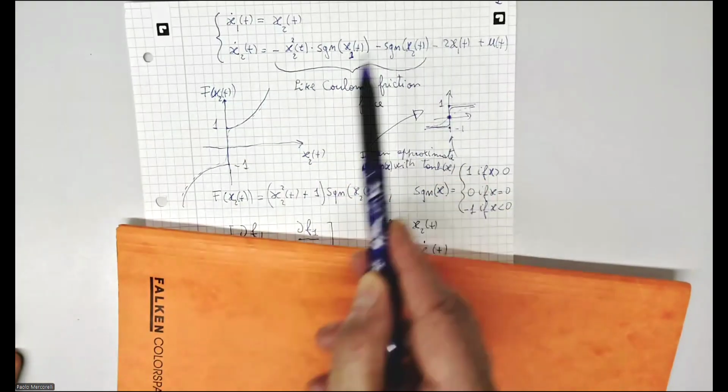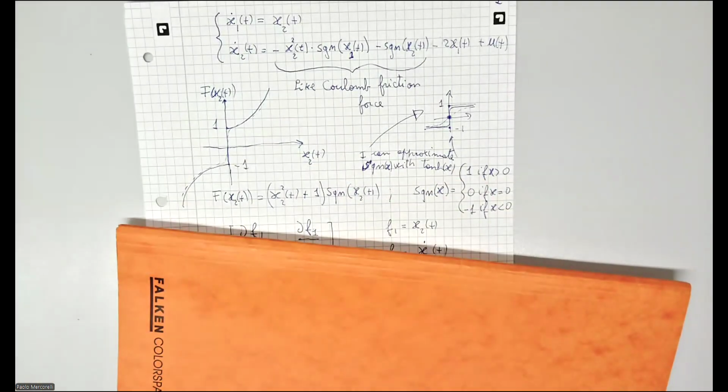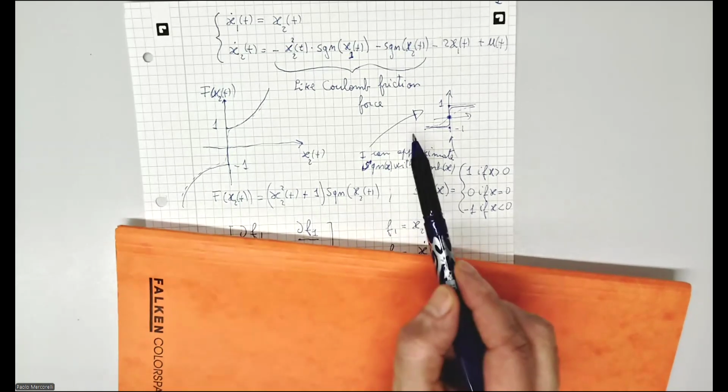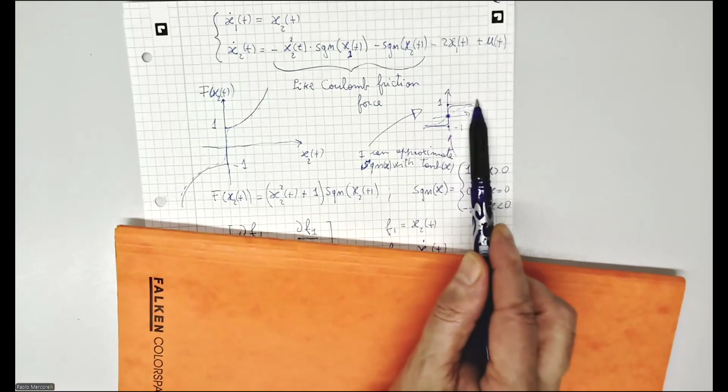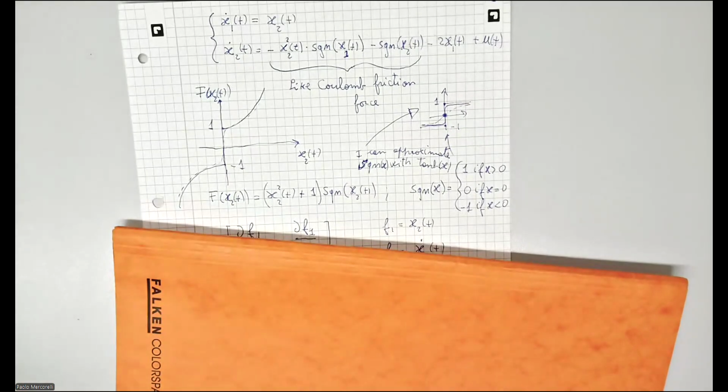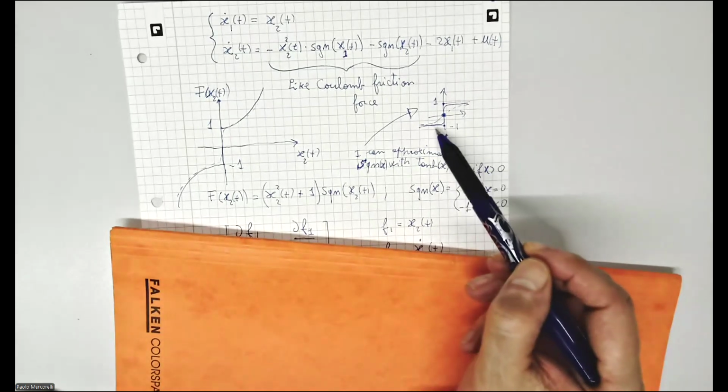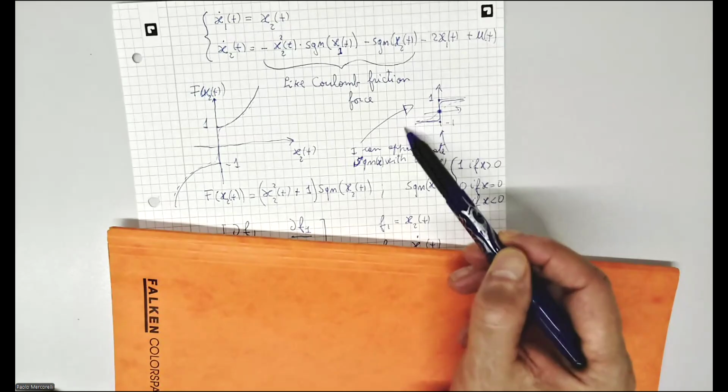If I consider this mathematically, we have a force which is not continuous. Now, physically, I'm not a good physicist, but I don't know if this is really a valid model. This means very often we approximate this function here with a hyperbolic tangent, which changes between 1 and -1, or 2 divided by pi times arctangent.